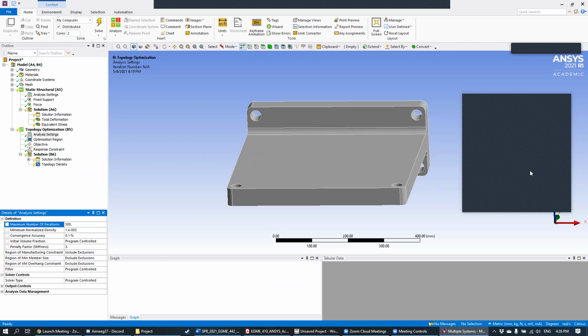Okay. And so the other quantity that we have to set here is something called convergence accuracy. Because what can happen a lot of times, and probably what's going to happen here, is that sometimes the optimization algorithm is going and you're guessing new solutions, and it's already so good that your new guesses don't really change that much from before, right? And so in those cases where you've already searched the entire space and there's really nothing left to search, then we say that the optimization algorithm has converged. And so this sets the accuracy for that convergence.